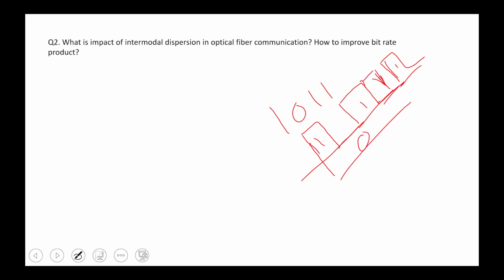So this is the waveform of non-return to zero, and in return to zero, it will be like this. This is non-return to zero. No, this is return to zero, it will become zero. Non-return to zero will be like that. Yes, sir, you are right. Because for zero we put 0 volt, it will return to zero again, and for one we put 5 volt or 2 volt.